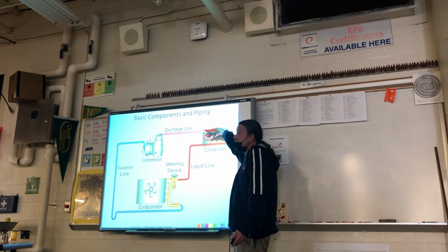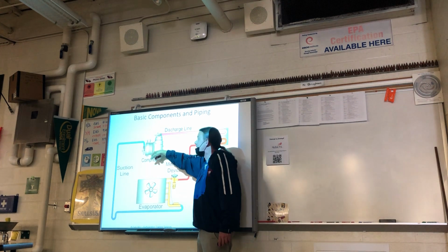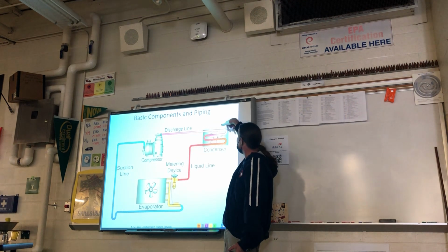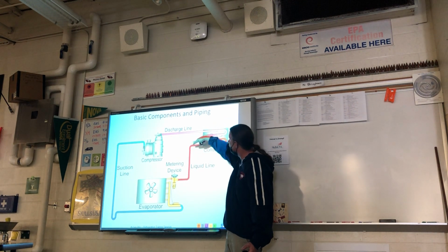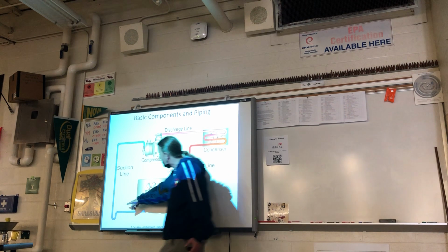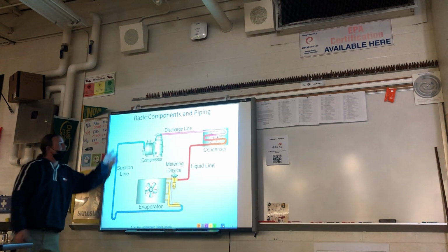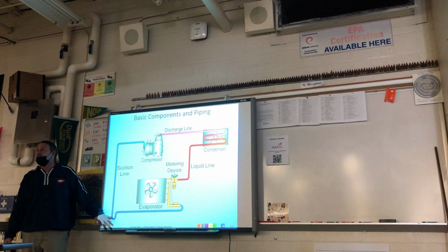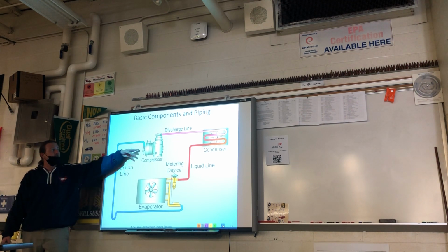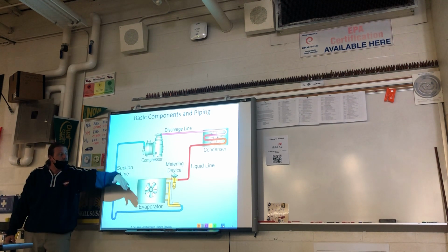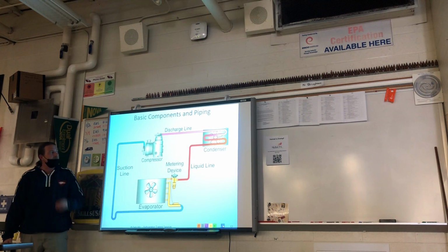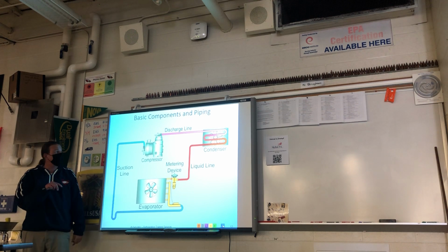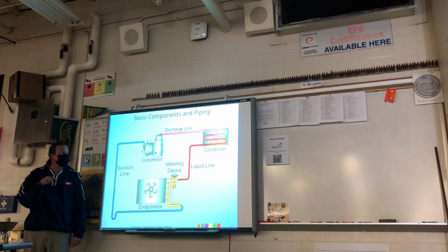But it's got to do it because we need that oil in the compressor, and the refrigerant and the oil mesh so well together, so no chance for it to all stay there. Some comes out with the refrigerant, and eventually it collects here, and we want it to draw back up into the compressor when it first starts up. So it'll collect here, and then once that oil's all here and that compressor fires up and the refrigerant starts flowing, then it can get the oil back in the compressor, and you can see it in the sight glass right there if you look in the semi-hermetic. As long as you see oil in there, we're good.